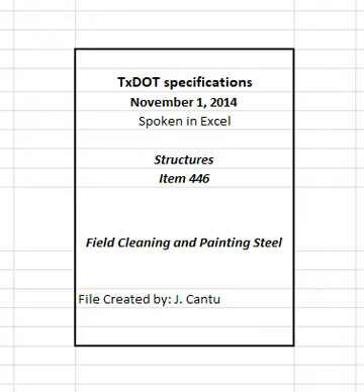4. Construction. 4.1 Qualification. Certification of the cleaning and painting contractor, subcontractor, or fabricator is required as follows. Submit to the engineer documentation verifying SSPC QP1 certification for work requiring the removal or application of coatings. Additionally, submit to the engineer documentation verifying SSPC QP2 Cat A certification when work requires removal of coatings containing hazardous materials. Maintain certifications throughout the project. No work may be performed without current and active certifications unless otherwise shown on the plans.